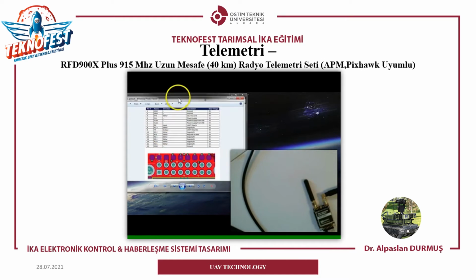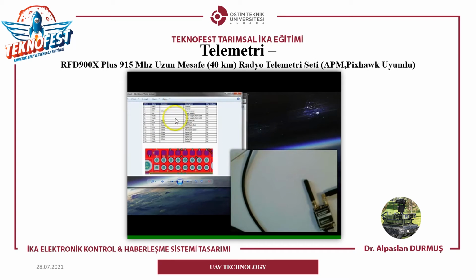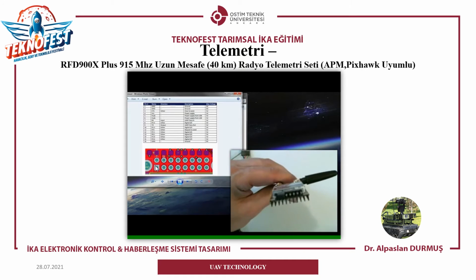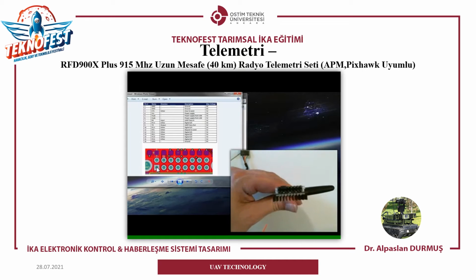Also on the RFD user's guide on the product page, you'll find the same diagram. This number 1 on the diagram, this is the pinout of the header on the bottom of the radio. So this 2-row header that is on the bottom of the radio is this pinout here. So number 1 on the bottom left, which is ground, is also this bottom left pin on the header. So you can see the 2 rows of the header here.